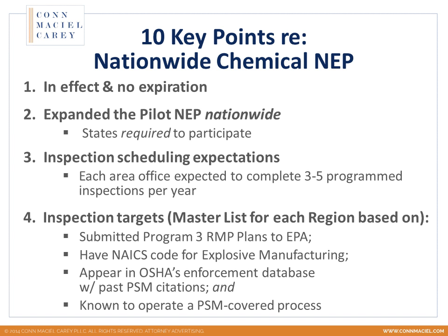They've created a master list for each region based on RMP submissions to EPA. If you are a program level 3 RMP submission, your name has been dumped onto this master list for the chemical NEP for OSHA. If you have a NAICS code under the explosive manufacturing category, you're on this list. If you appear in OSHA's enforcement database because you have had previous PSM violations, you are on this list and likely to be inspected under the NEP program. And then if you are otherwise known to operate a PSM covered process.